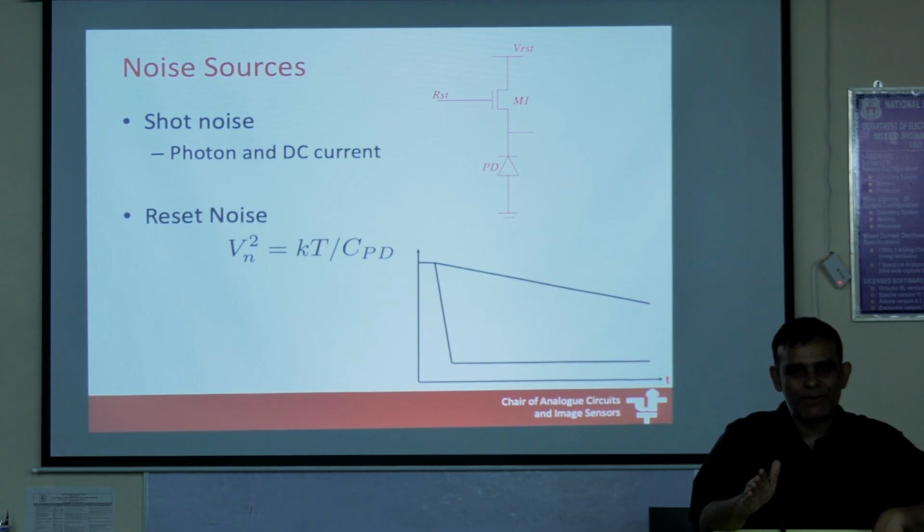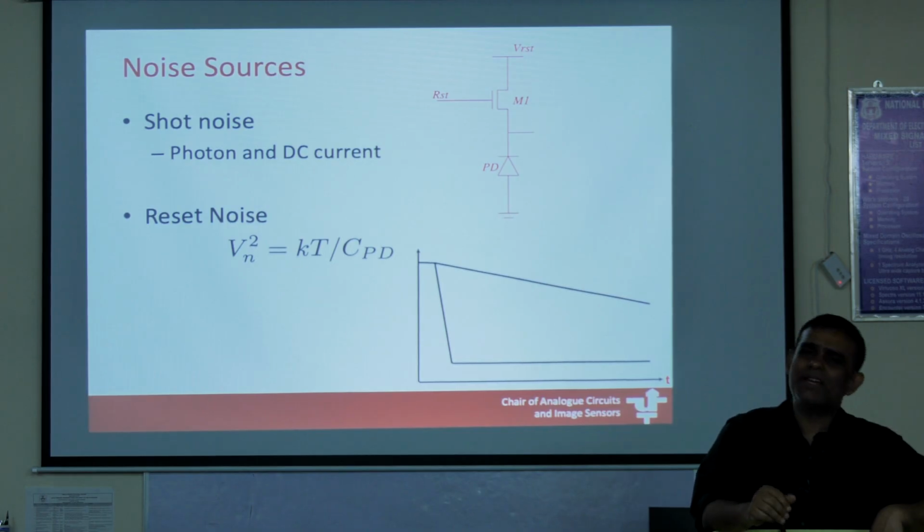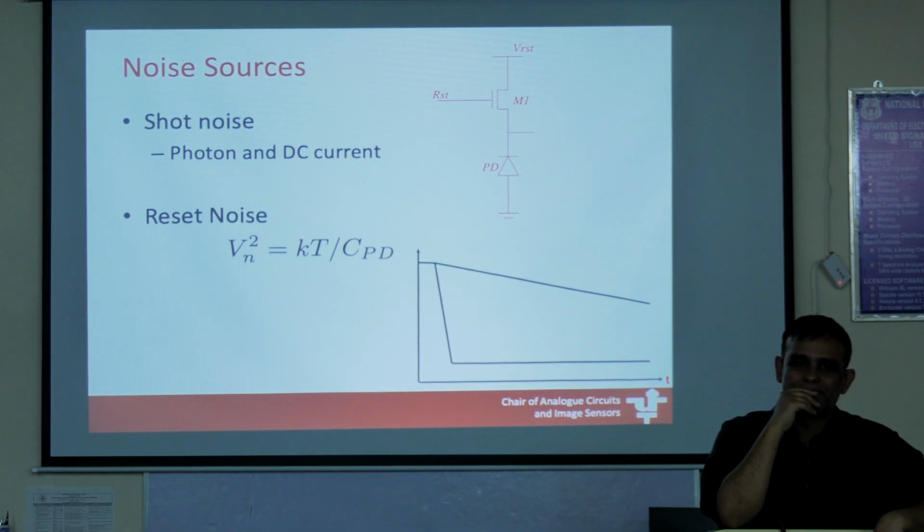So we're going to get flicker noise in the readout as well. But the biggest killer is not that. The biggest killer is Johnson noise, as everywhere else. We get noise not during the time of capture. Remember I told you, right in the beginning we reset the circuit.